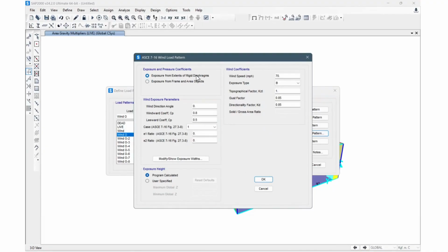One is a rigid diaphragm. This one is for when we analyze a high-rise building, and the slab acts like a diaphragm. So I think we will not use this one for now. We will use only the area because it's just the wall from outside. So we will use the area pressure, and then we can put the coefficient. If it's an open structure, we click the other one too. But if it's just a closed structure, we will use object area. Okay, now click OK.